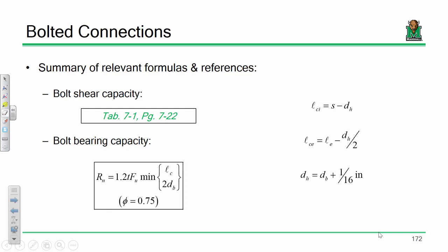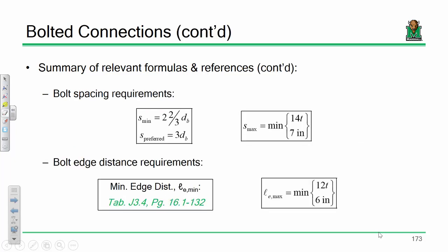So you have an Lc value for the edge bolts, and an Lc value for the interior bolts. The formulas are pretty easy to derive. Remember, we're using physical dimensions of the hole, so we use 1/16 of an inch and not an eighth. Now, that's good, great, grand, and wonderful for your strength calculations.